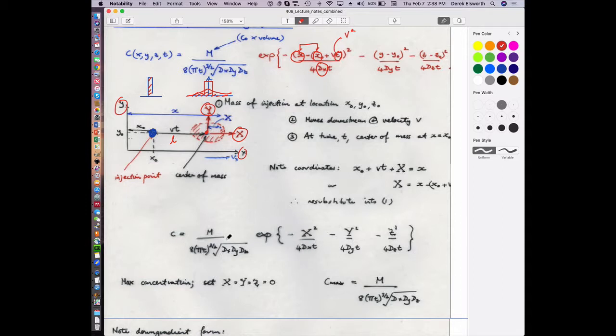It's always a bell curve. It always has a mass of, in terms of kilograms of pollutant that's present within the system. The dispersion coefficients in X, Y, and Z directions for longitudinal and transverse dispersion. The time since it happened, these coefficients, and the location relative to this coordinate system here.